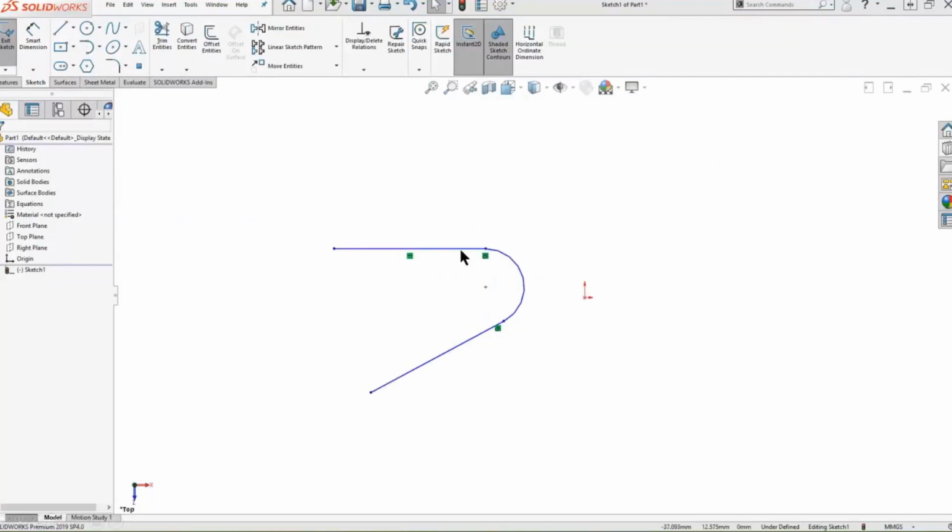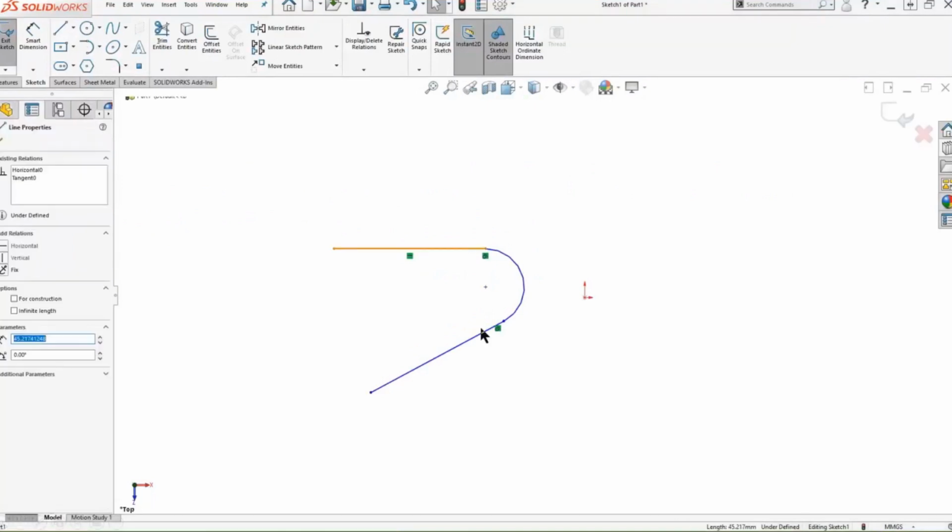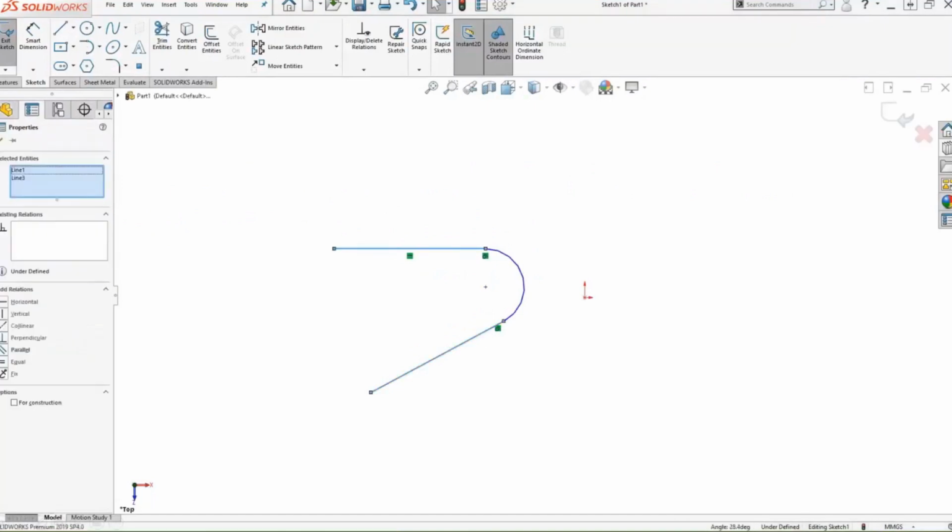So here's that hold down the Control key action, the two lines up to the sketch toolbar and the point. Super, super quick. So it's a reference point at the intersection. You could then use that to dimension to really do whatever it is that you need. So that's kind of the hidden tool to generate that virtual sharp inside of our SOLIDWORKS sketches.